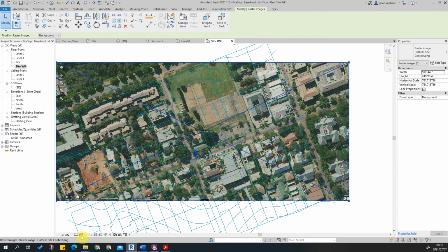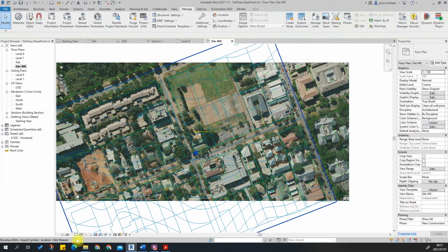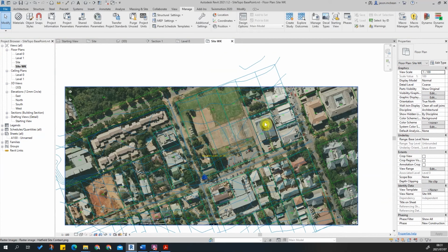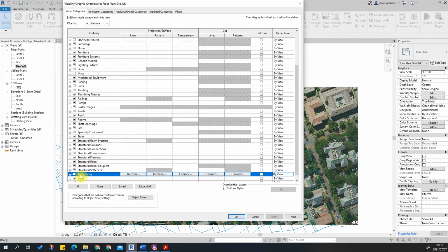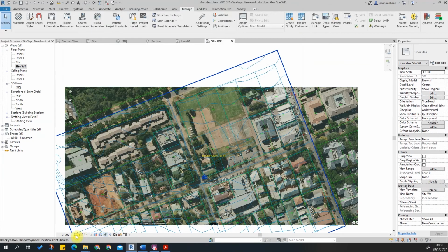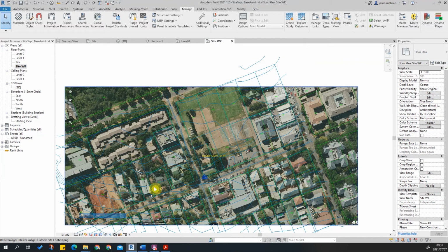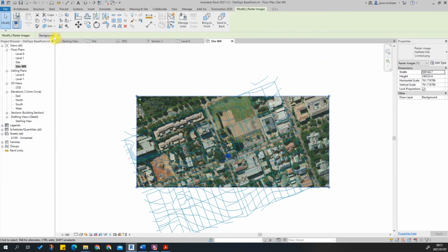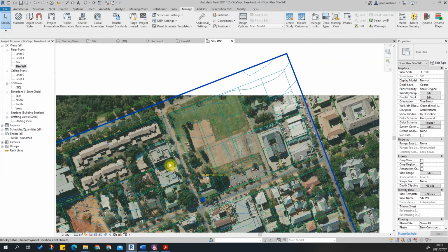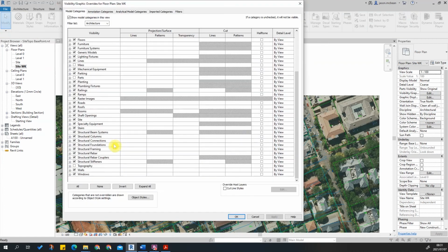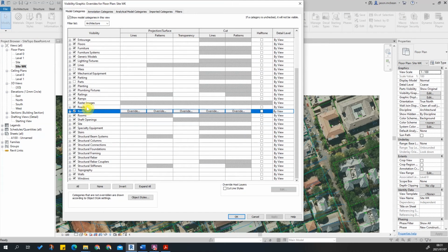Just remember, if your topo surface was on, you'll need to use the wireframe mode to start seeing through your topo surface. So let me just bring that back. Topography, switch that back on, and I'll switch this back onto hidden. Just make sure the image is below background. Okay, let me just see why that's not on. VG, topography, press apply.